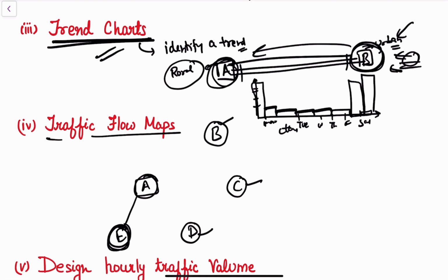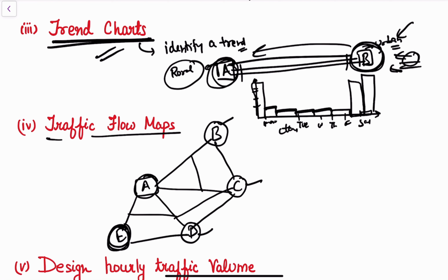So there are a number of interconnected roads in this section, right? So what we can do is we can do a traffic survey throughout the road section, and see what is the flow map in which the vehicles are moving, what is their origin, what is the maximum traffic volume or origin station, and what is the destination station, and what road pattern are they following, right? So from there, that can again get verified through the traffic volume study.